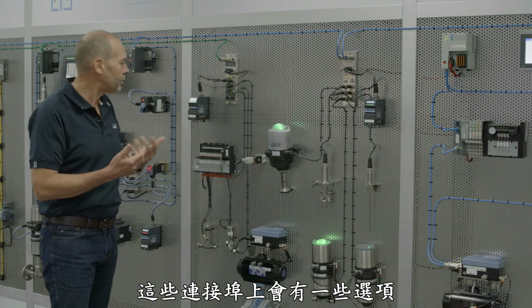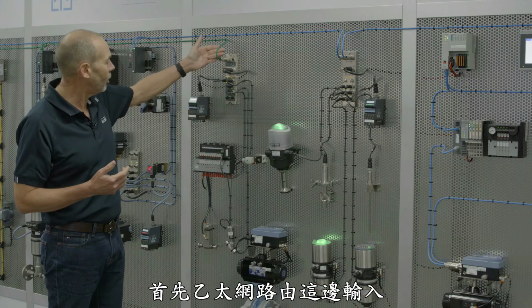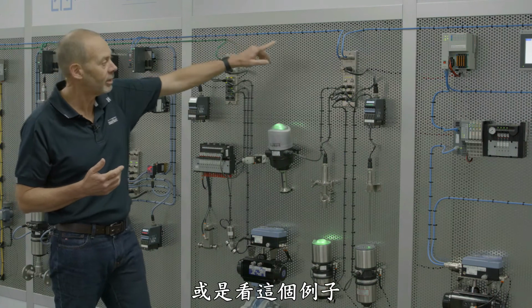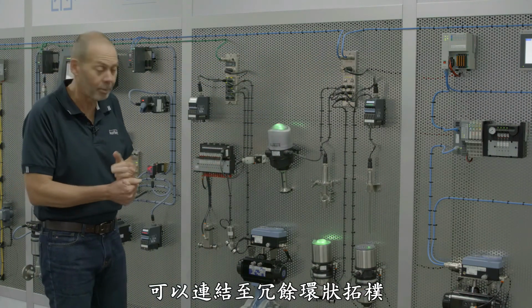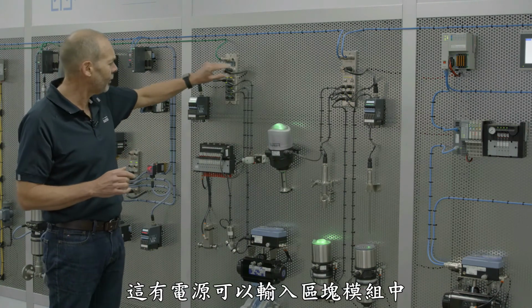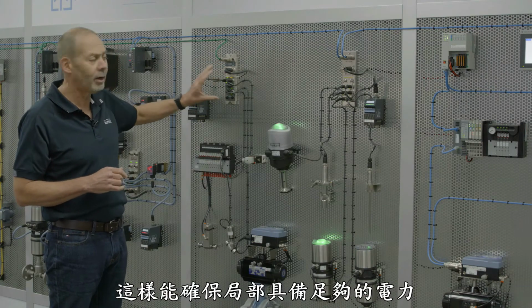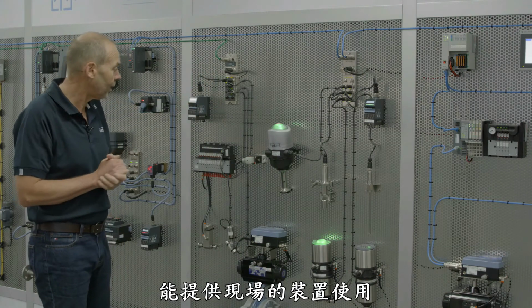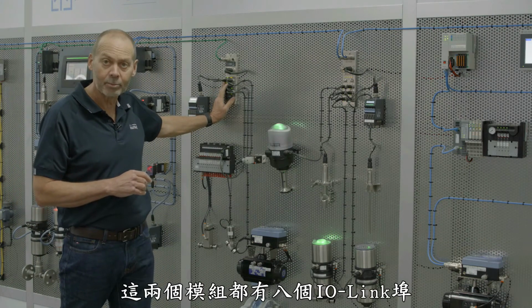So a couple of the options that you can do with any of these ports on here, firstly you have your Ethernet coming in and out necessarily. So in other words, as an example here, which means it can go onto a redundant ring topology, which makes it easy to put into the field. You have an additional power supply that can be brought into the modules, so therefore you've got enough power locally to be able to power whatever devices you've got installed. And then you've got in these instances, both of these examples have 8 IOLink ports.